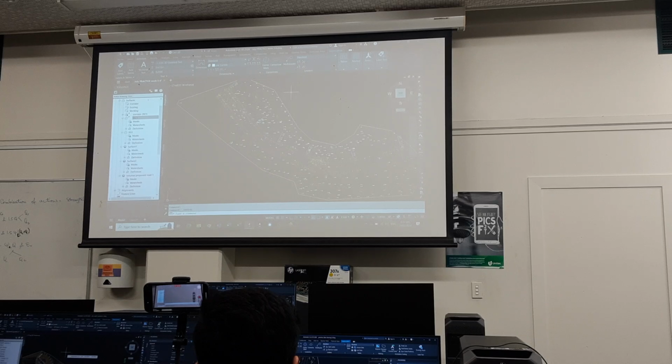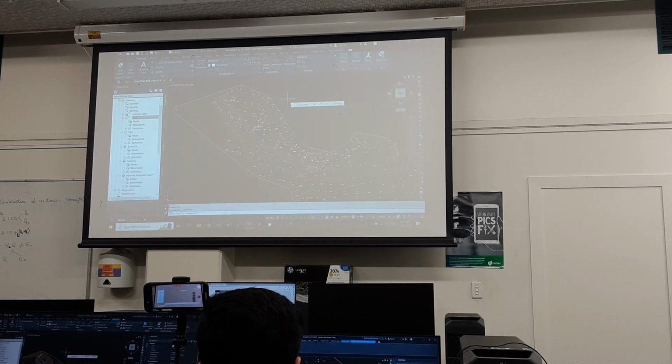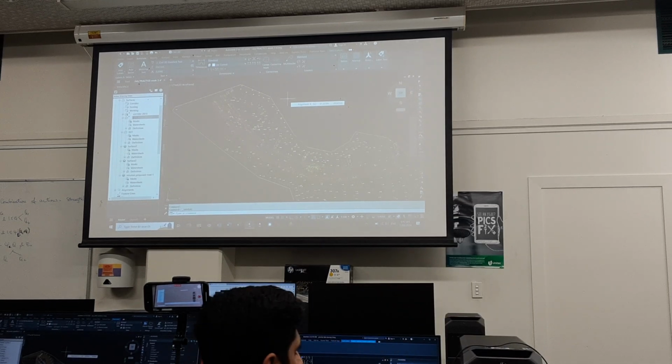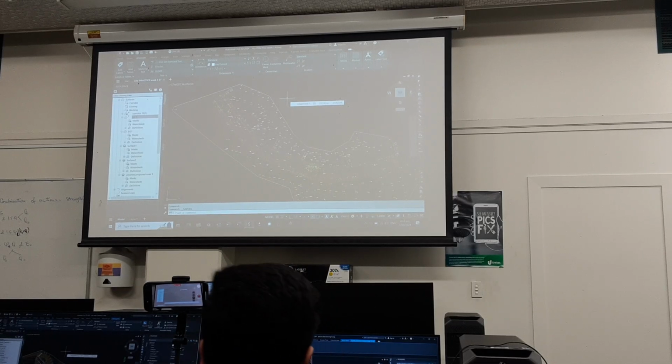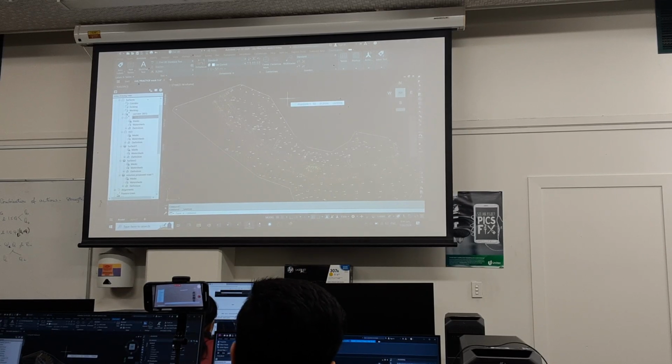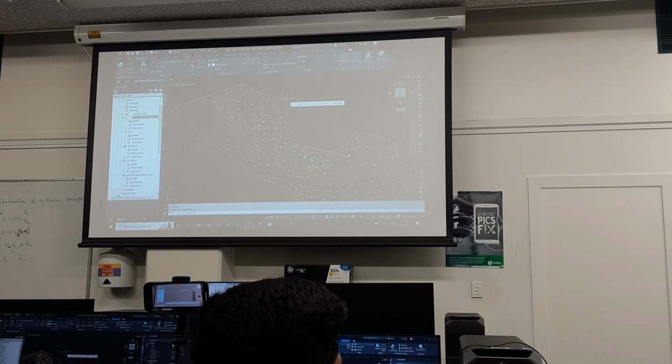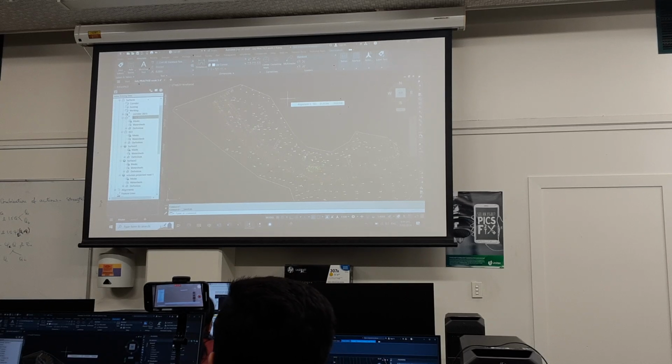Just remember they've got those options, and that single one is quite useful. If you've got something in the corner you can't get to, just go back, restart the process, choose that single one, and just really click. You'll have a contour value. If you've got the odd one where you need something special. So I'll be opening your drawing, your Civil 3D drawing, and looking for those contour labels, and I'll list them. And they need to be at a height that is correct, and they need to be on all the contours.